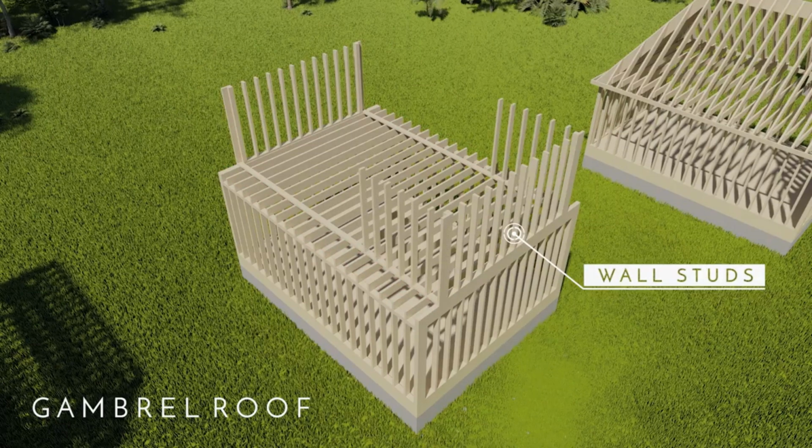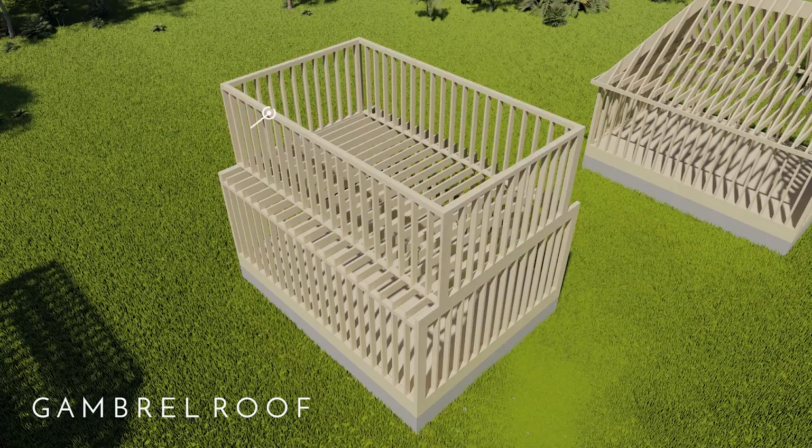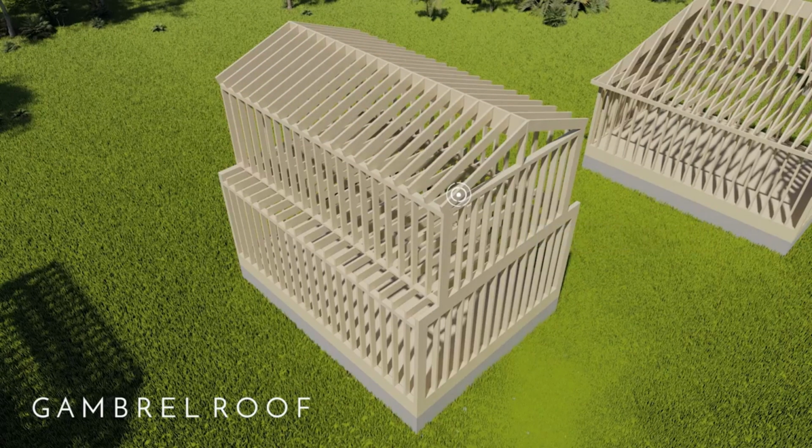So basically what we did up here was we built another box. It has the sole plate, the wall studs, and the top plate again. So here we have the two posts that sit at the end. And then we have the ridge. And the first set of roof rafters will connect from the ridge to the top plate on the second floor here. So an easy way to think about this is that there's a separate gable on top of this sort of box here. And here are the rafters that make up that second steeper pitch on the side.